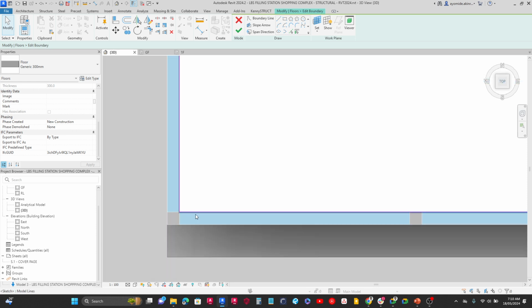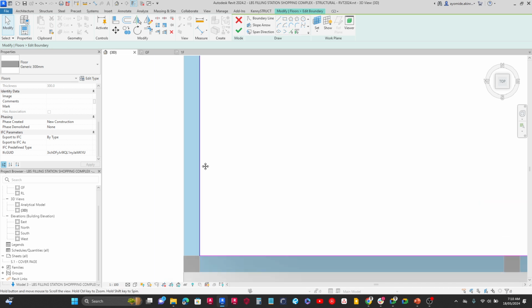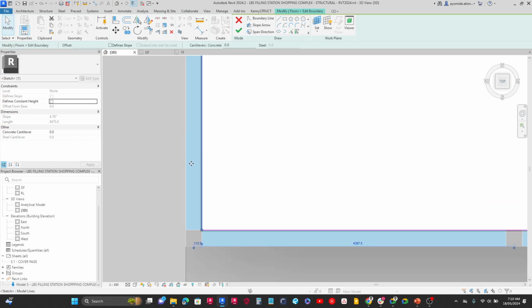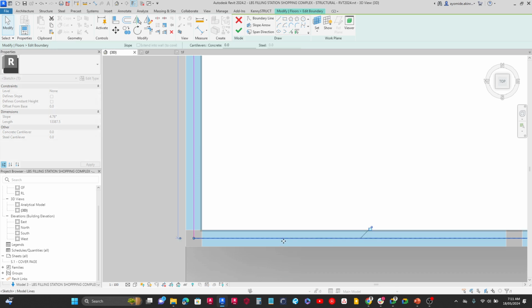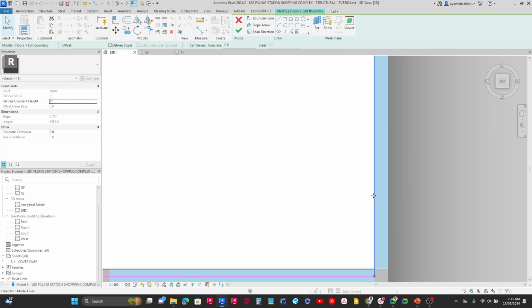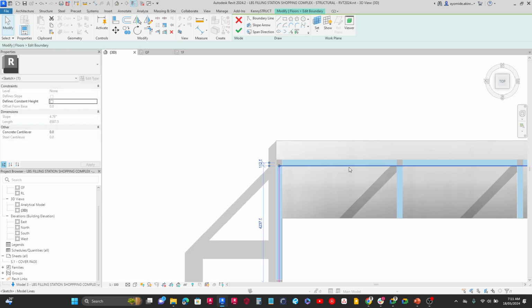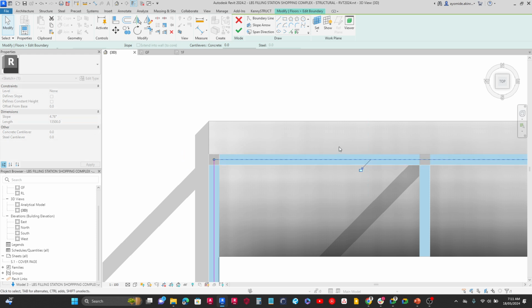And right now all of them have been set to show in the middle of the slab, I mean towards the interior of the slab. So what we are going to do is drag them out a bit. I'm going to drag everything to the center. Now this is how us engineers would prefer our slabs to be, and you'll understand that when we get to another topic later on. So I'm going to drag it to the center lines of the beams and the columns, because that's the point of contact. Let's drag it to the center lines like this.